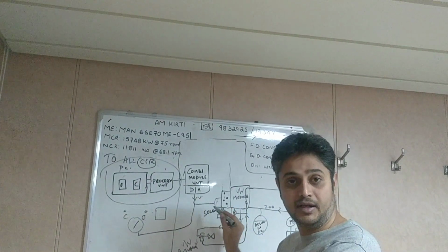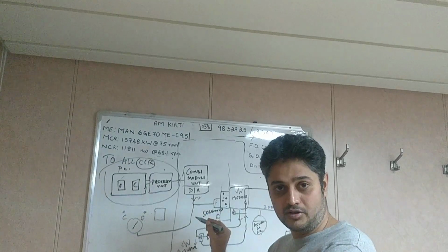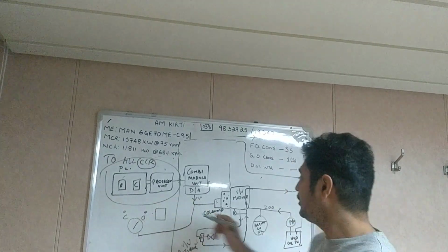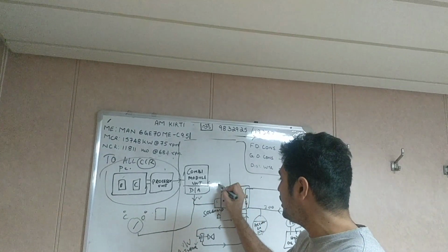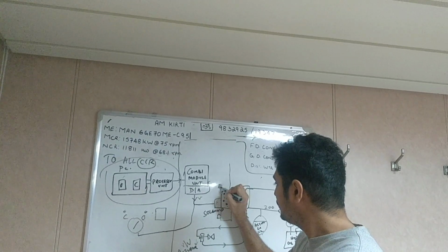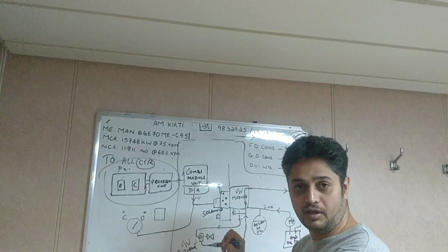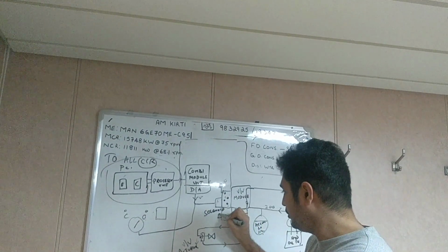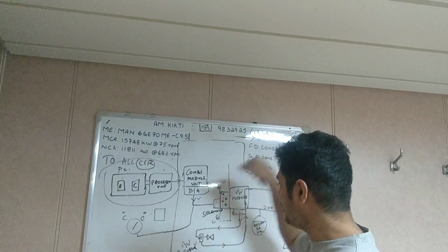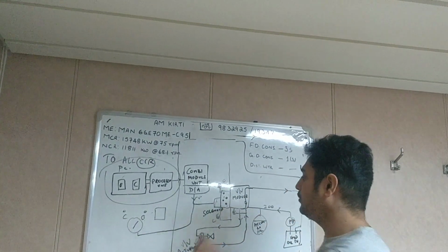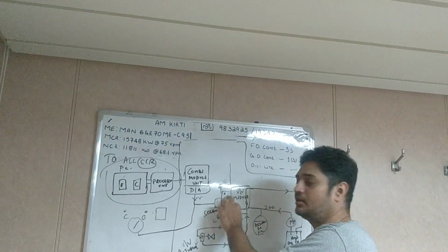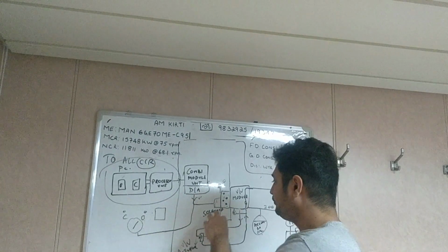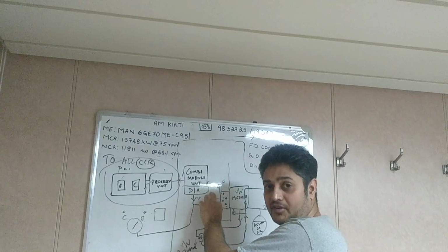First, whether the solenoid is getting energized or not. That is the first thing you have to check, whether the signal is coming here to the solenoid. First thing, this has to energize, no? Because there is another way. There is one manual push button here at the proportional valve. There is a manual push button, open, and you can assume the other as close. If you press this manually, you are manually pressing the spool, so you are manually energizing the solenoid.